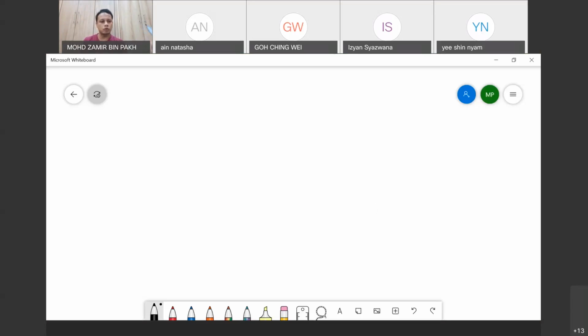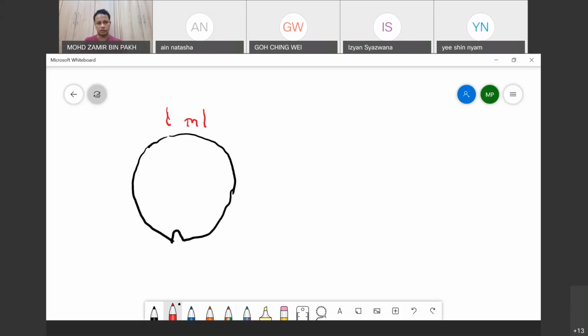Okay, good. So from the top view, assuming this is your wafer, okay, that's the notch. If you have a good resist coverage, for example, you're supposed to dispense 1 ml, and the system is dispensing 1 ml of the photoresist before it is spin coated, the coverage you will see is very uniform, and you won't see anything weird on the surface. So basically, the whole surface is covered well.